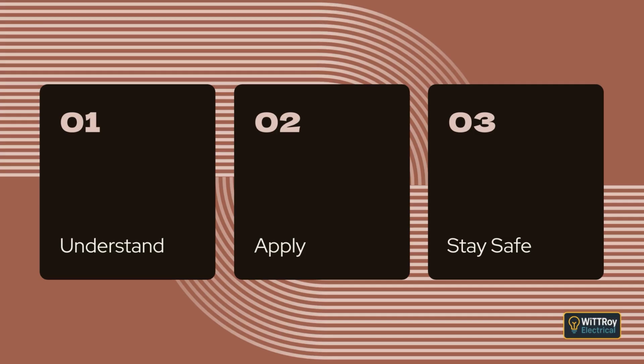Clause 3.7.2.11 Earthing conductors. If the earthing conductor is joined by soldering, the joint must be secured by additional mechanical means so the conductor remains firmly held even if the solder softens. Tunnel-type connectors used with earthing conductors must have either 2 screws or 1 large screw able to grip the conductor without cutting it. Where clamping over insulation is not necessary, bare conductors must be clamped directly using suitable ferrules or plates.